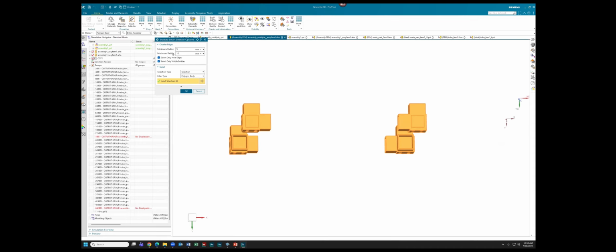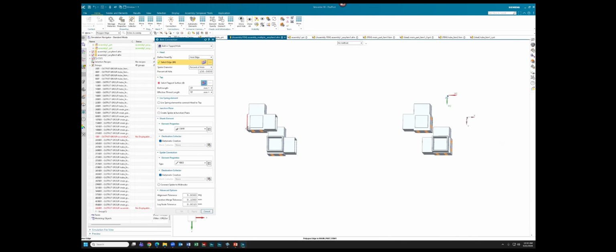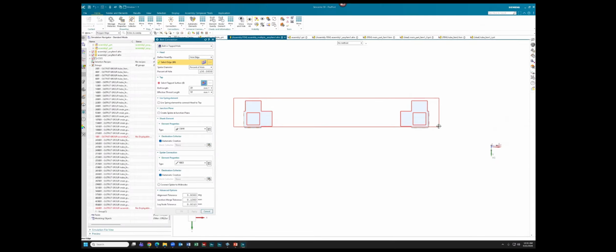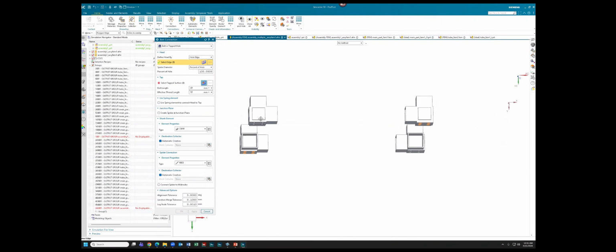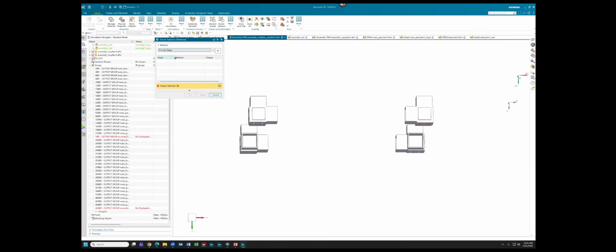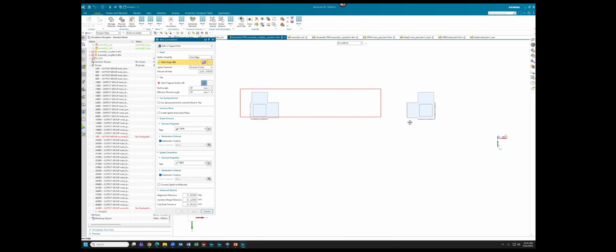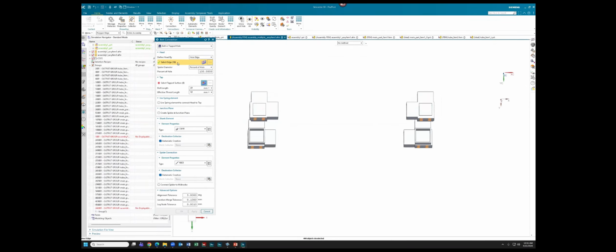And then you can also give it a min and a max radius, and that'll be how it determines what it wants to select. So you can see it grabbed a bunch of edges, some additional ones that we don't even want, but then we can actually do easy things like just deselect some of these edges. So yeah, really helpful feature there, something I definitely recommend taking advantage of, these smart selector options. Actually accidentally deselected some additional ones, so I'm just going to go ahead and run that through once again. There we go. All right, so we have our 16 edges that we are looking for.